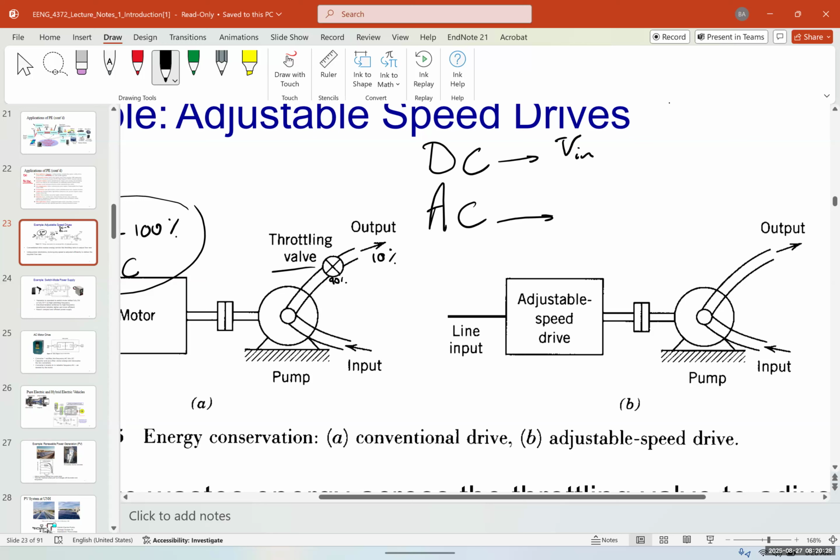One is the number of poles when you have an AC synchronous motor. And again, you don't have any control over the rotor's current, or on the frequency. Obviously you can't change the number of poles in an AC motor, because that's fixed when you build it; it has 2 poles, 4 poles, and so on. But what you can change is the input frequency. The higher the input frequency is, the higher the RPM would be.